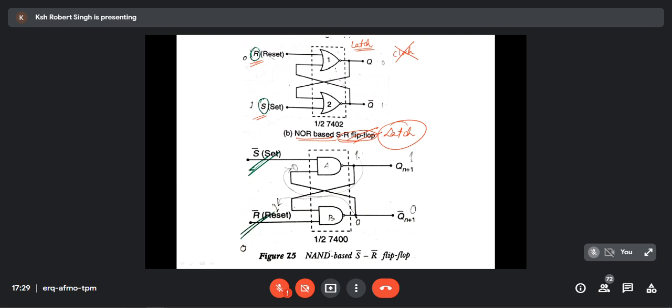That is level sensitive. In another sense, it is event triggered. What is an event? What is R, what is S? R is the reset input pin, S is the set pin. They just give the names R and S, that's why it is called an RS flip-flop or RS latch. R can be sometimes 0, S can be 0, R can be 1, 0, 0, 1, 1, 1. Any conditions can be there.